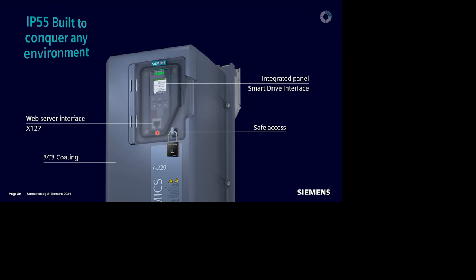So we don't need any external tool, although the drive is integrated in TIA Portal, Startdrive. But once we receive the drive, we can just connect the patch cable. We can access the integrated web server and do commissioning, diagnostics, monitoring, backups, and restores. And we can do every kind of setting just via this service port.